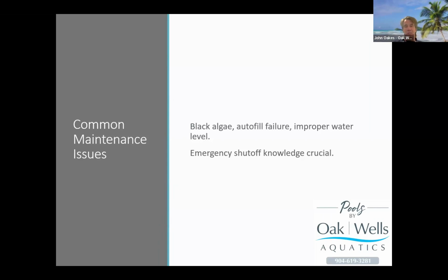And so in the swimming pool, the way that we try to prevent black algae from growing is by keeping the water chemistry right, but that's not the only thing that needs to happen because the water chemistry should reduce the incidence of black algae, but algae, particularly black algae, reproduces by the use of spores, which are like little teeny tiny seeds that'll float in the air. Those spores get into the swimming pool and they'll settle on horizontal surfaces, for example, like the bottom of the pool or the cove, which is where the wall turns into floor,